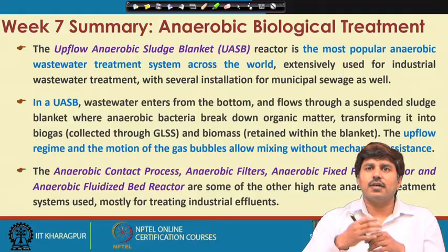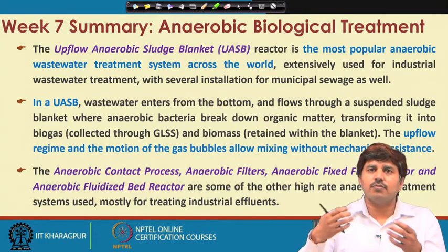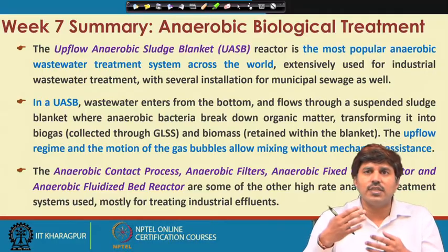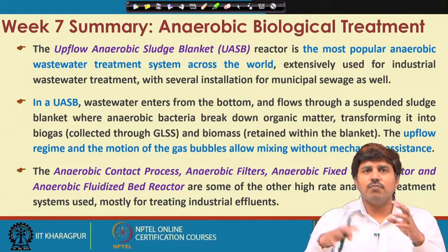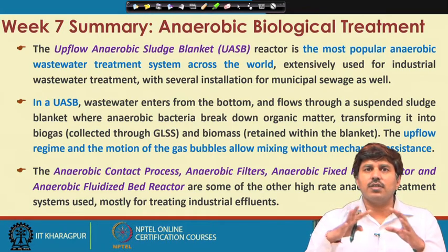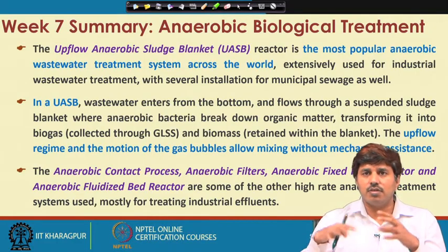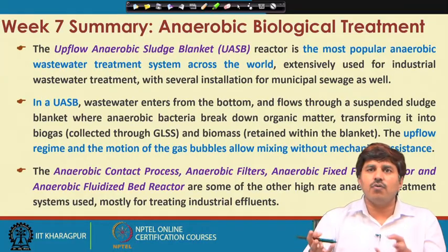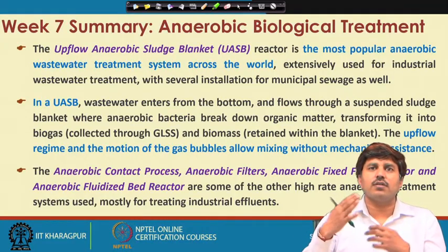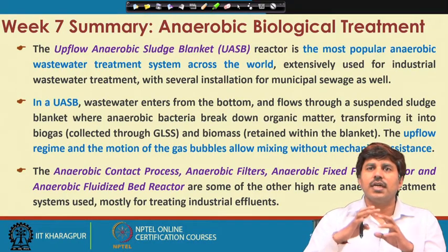Some sludge mass or biological organisms also come along with the gas particles as the water flows up. This upflow regime ensures the mixing in the sludge bed itself. There is gas motion and an upflow regime of water movement, so this ensures that enough mixing is there and we do not need any mechanical mixer in the system.